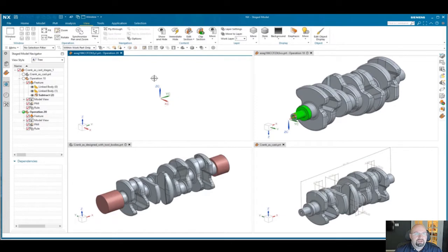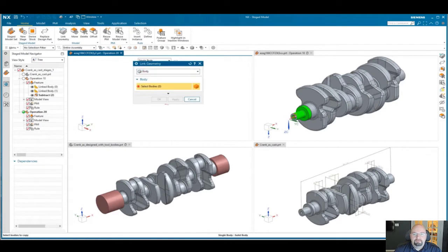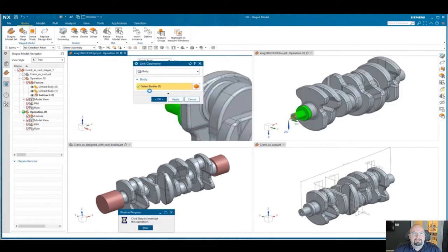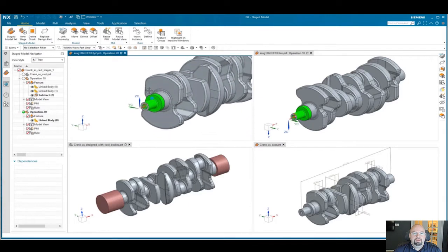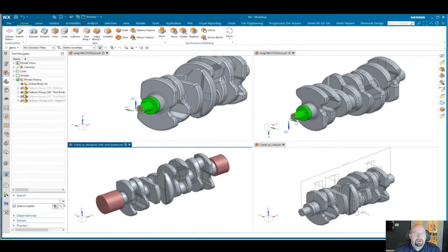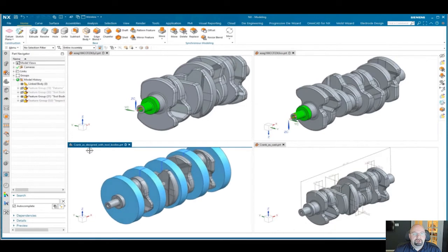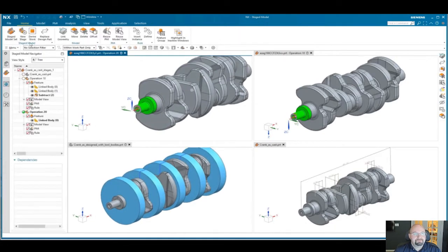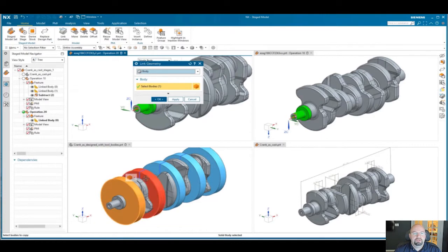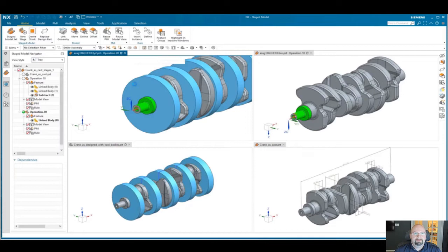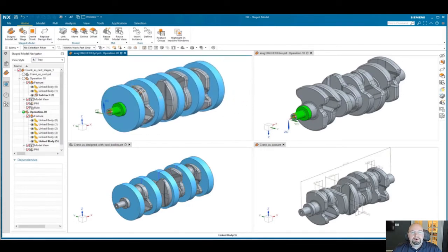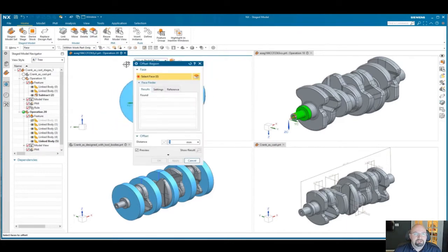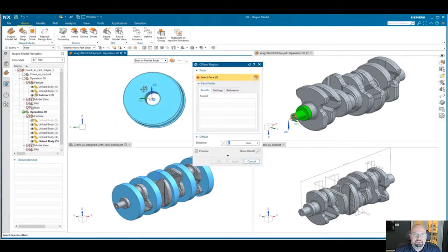As we continue, we add an additional stage here. So we're going to go ahead and link the as cast body from the previous stage with the two ends that have been machined. Go back to the final production part, and we're going to turn on some additional tooling bodies here. We will link those into our new stage and use those to subtract some material from that stage. So you can see the benefits of these capabilities of reusing geometry from additional parts by wave linking those bodies into the additional stages.